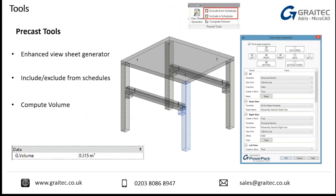We can now generate views for a sheet. Again, this is a function that's been there for a few years, but what it won't do is auto create the views on your sheet. It'll create a sheet, create the views separately. You've still got to set the sheet up. You've still got to drag the views onto that sheet. What this tool does is basically the view sheet generator will automatically create the views, create the sheet, and put the views on the sheet for us.